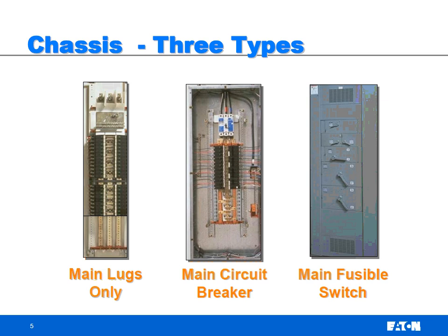And often these are, because the general rule of thumb is that a 100 amp breaker is required to feed 100 amp cables, which is required to feed a 100 amp panel board. So just by how you're going to have to do it anyway, the 100 amp breaker is going to have to be sized to protect this 100 amp panel. So if you put the 100 amp breaker in there, this breaker here should really be identical to the one you'd have upstream in the switchboard.